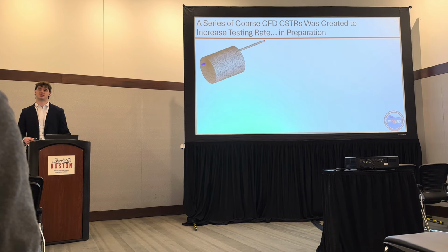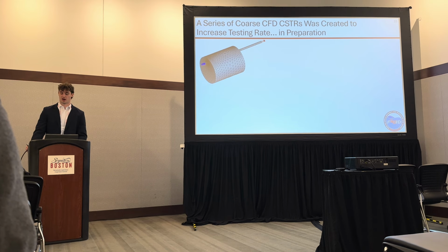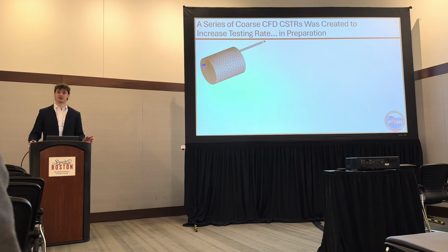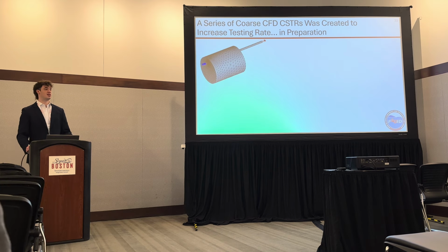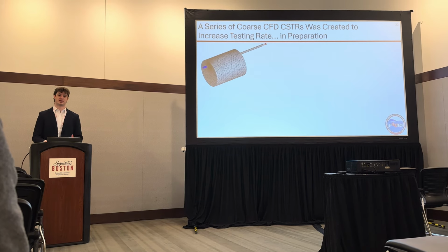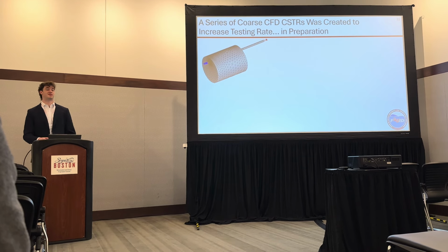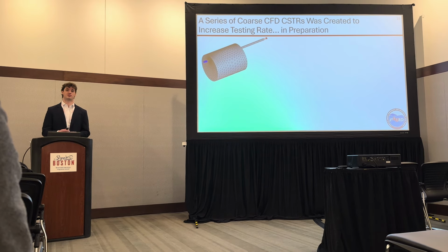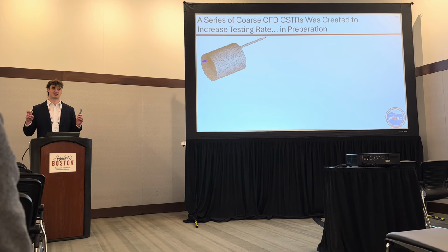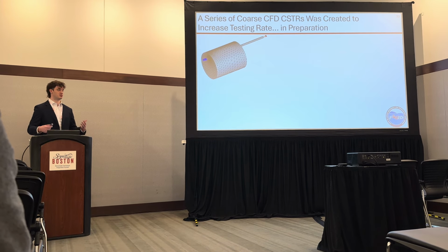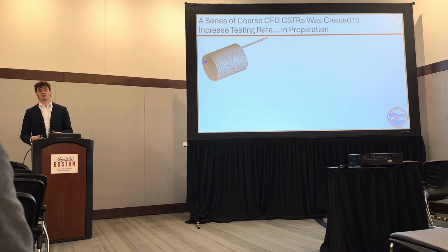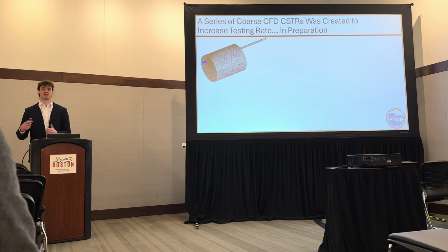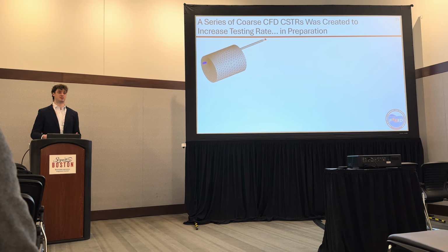Now, as I mentioned, we are using CSTRs for this study. We coarsened the CSTR to the point that we didn't believe was possible at the beginning, and that is another paper that is in preparation, but I'll give you a little bit about it now. So we started with a CSTR of around 65,000 tetrahedral elements, and we used TETs on purpose to make it more numerically diffusive. We wanted that perfectly mixed CFD CSTR, so the more numerical diffusion, the more mixed it'll be. But this didn't take 2 years to run to convergence, but it still took 2 weeks, and when we were running dozens of tests, that was still a little bit time prohibitive.